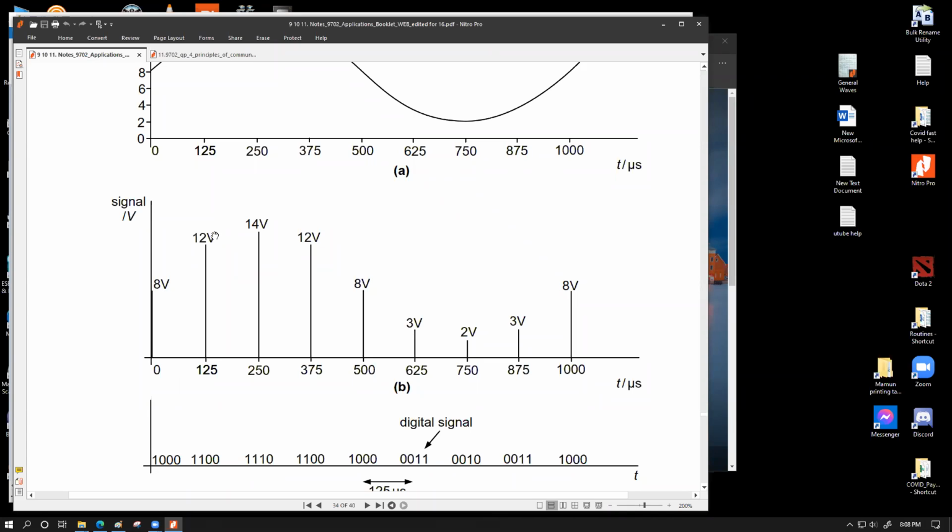At this 125 microsecond mark, you once again have 12 volts, which you are receiving exactly at this 125 microsecond mark, and then you have these 4 bits on your hand. So there is 1100, and then you don't have any more data for the next 125 microseconds. That's how it's produced. So the information that we generate in the process of sampling is produced instantaneously. That's the important bit, not over a duration. So these are the data. This is the type of data which are produced in 4 bits. So this 4-bit is one number, this 4-bit is another number. This is what we call parallel data.